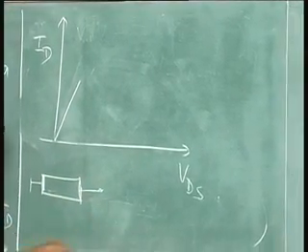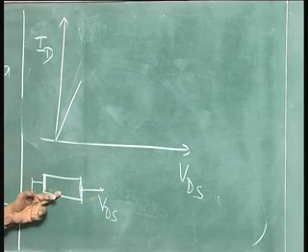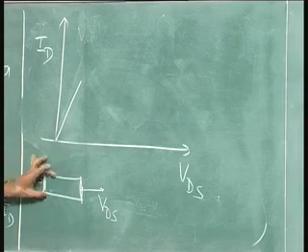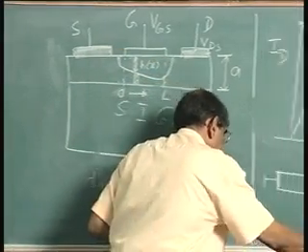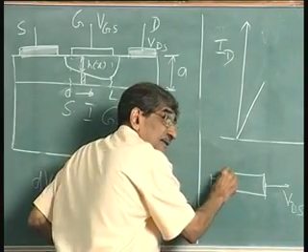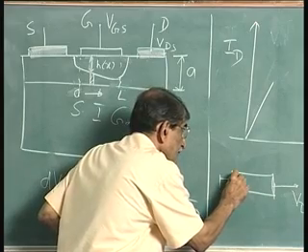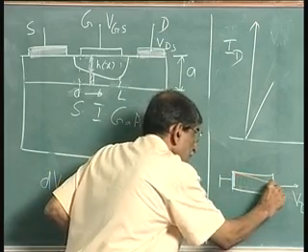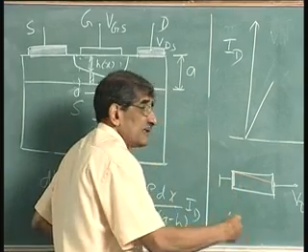It is so simple. We are talking of a resistance R with the channel length and thickness equal to whatever was there. Now, when you keep on increasing this voltage, this remains the same, but the channel falls, not exactly linearly, it falls in some fashion depending upon the voltage there,